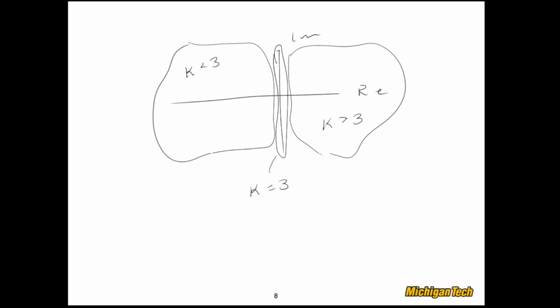So just to recap, we introduced the Routh array, and the focus is grabbing the characteristic equation of some transfer function, creating a Routh array, and then analyzing the first column. Now just using a Routh array tells us about roots, but we could get that from a root solver. The really powerful part of the Routh array is when you use it for design or for determining the range of some parameters K, K1, K2, K3, etc. for closed loop stability. And we did some examples with that.